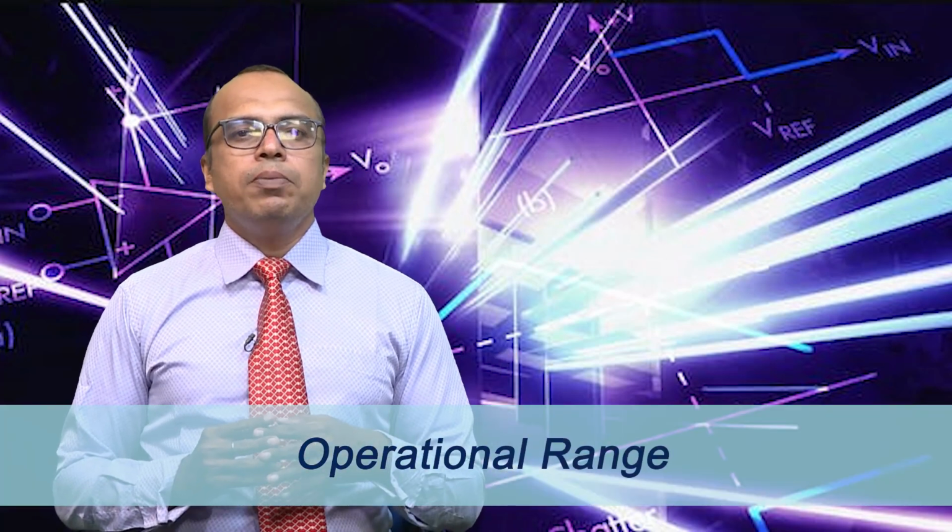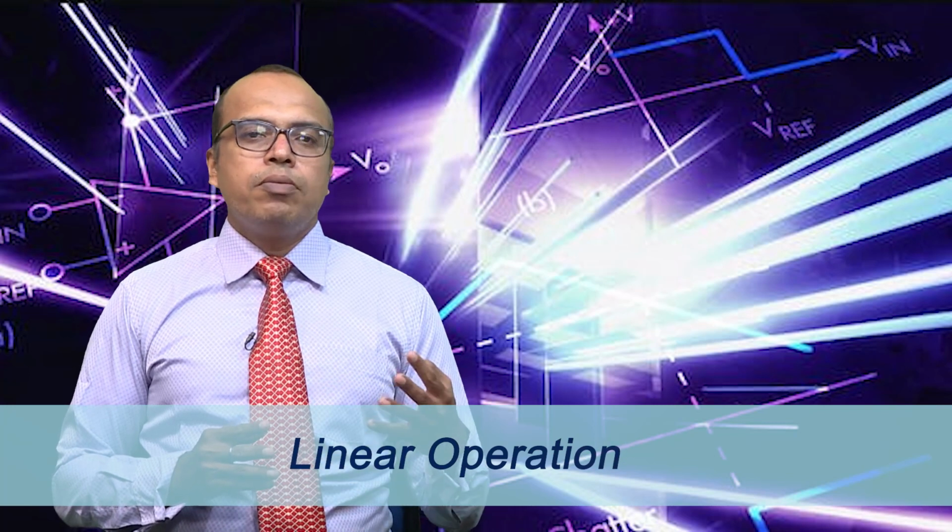Operational range. Op-amps typically require a dual power supply, positive and negative, operating within a specified voltage range. The most common power supply configurations are symmetrical plus minus VCC or single ended plus VCC and ground. Linear operation. Under normal operating conditions, op-amps behave in a linear manner and their output voltage is proportional to the difference between the voltages applied to the inverting and non-inverting inputs. Open loop and closed loop operation.